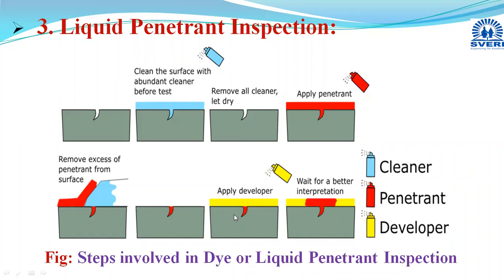We prepared one welding, and on that welded component we checked whether any kind of defect is there in that joint. Now, how is this liquid penetrant inspection done? Some steps are there. This is the first step. In the first three pictures, this is the first stage, that is the cleaning. Cleaning of that area or component is done, where we are going to determine whether any kind of defect is present or not.